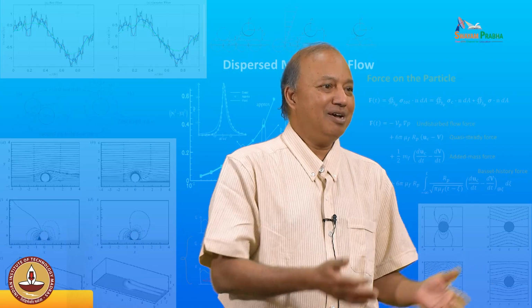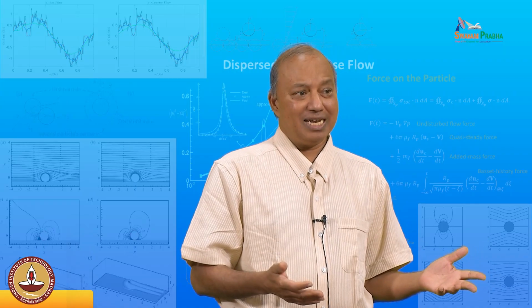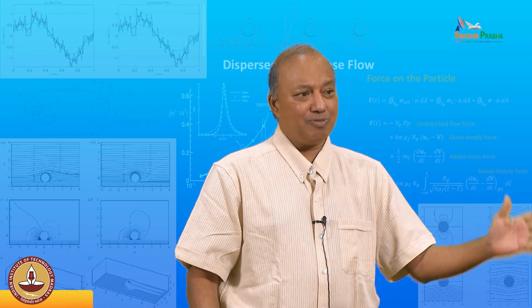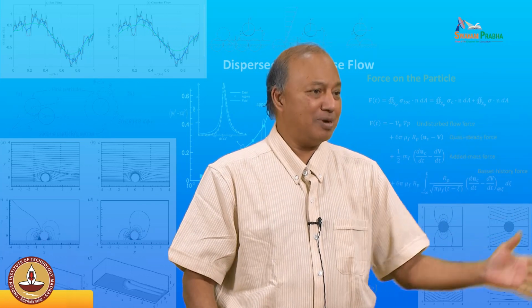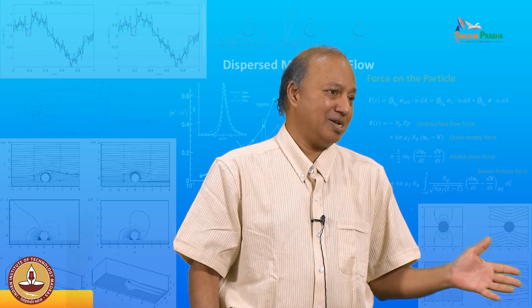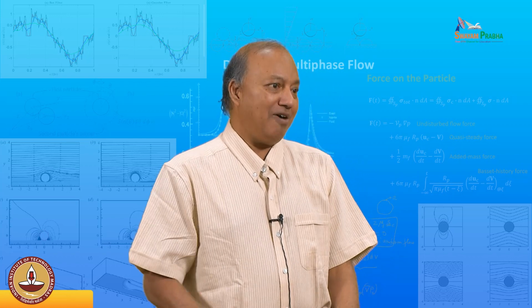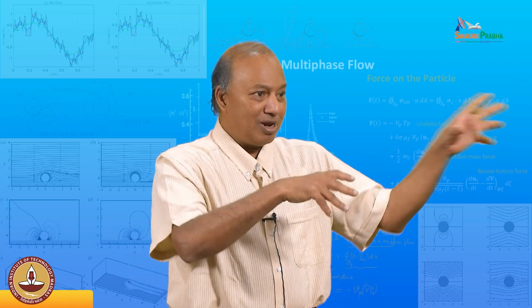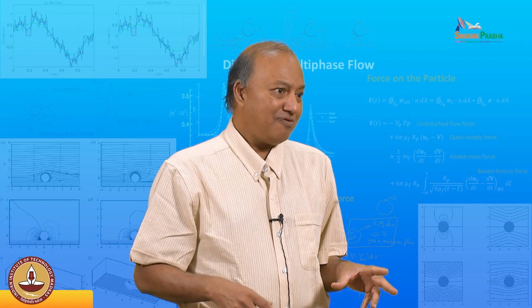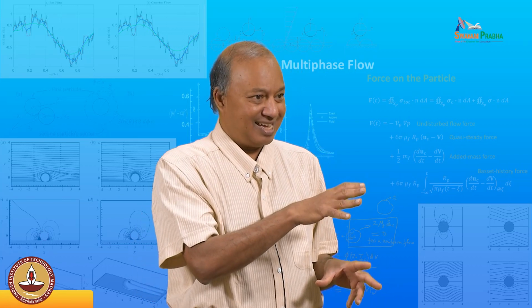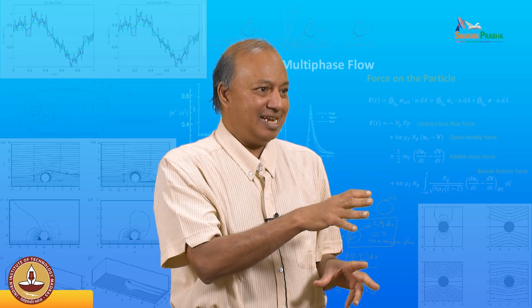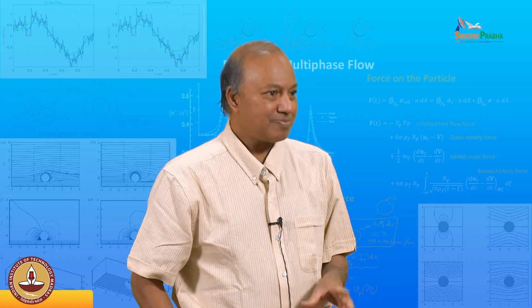But if you use ANSYS Fluent or something like that, the code is good, the answer is looking bad, which means something must have gone wrong. And an easy way to find it is to plot every term on the right-hand side of your momentum equation and mass balance equation, and you can see what happened. There you will find, for big particles, and there are only a few of them, you may see a very noisy-looking feedback force, and that may be the root cause of the problem.